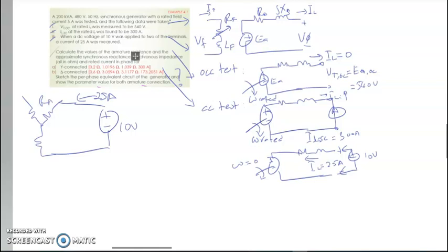The 25 ampere measured is conducting through 2 branches of RA, the armature system. From the equation V equals IR, we can obtain R, which is equal to V over I. So the resistance now is 2RA because we have a Y connection kind of construction.